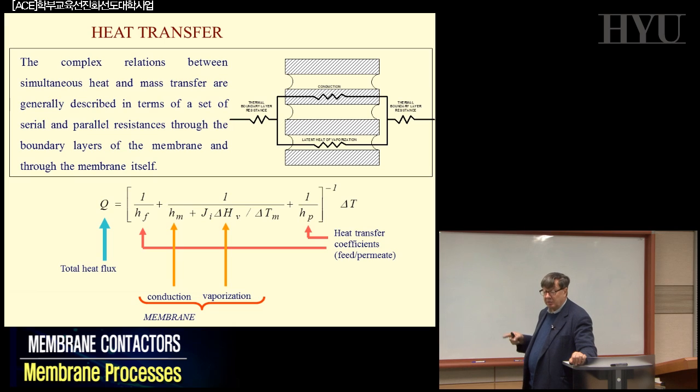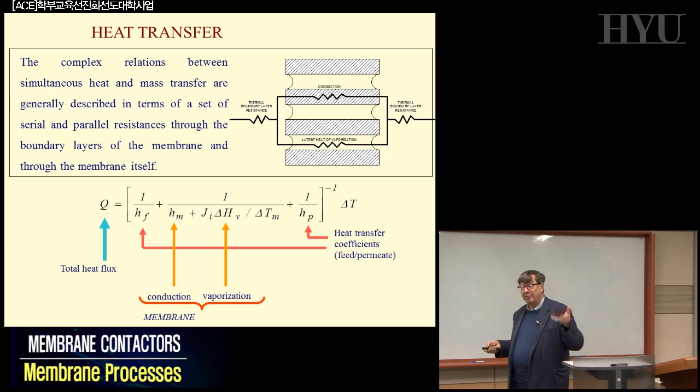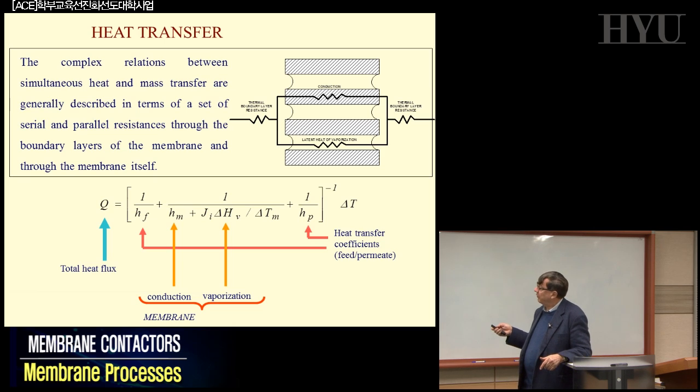Keep in mind today, in membrane distillation, with the materials we are using today and with the configuration we are using, basically 50% of the energy that we supply to the system is lost. We are not using energy for evaporating molecules and having the molecules go across, but we are using most of that 50% of the energy to warm up the polymer and create a different temperature between the polymer on this side and this side, which we don't need. Nothing happens. So it's just loss of energy.